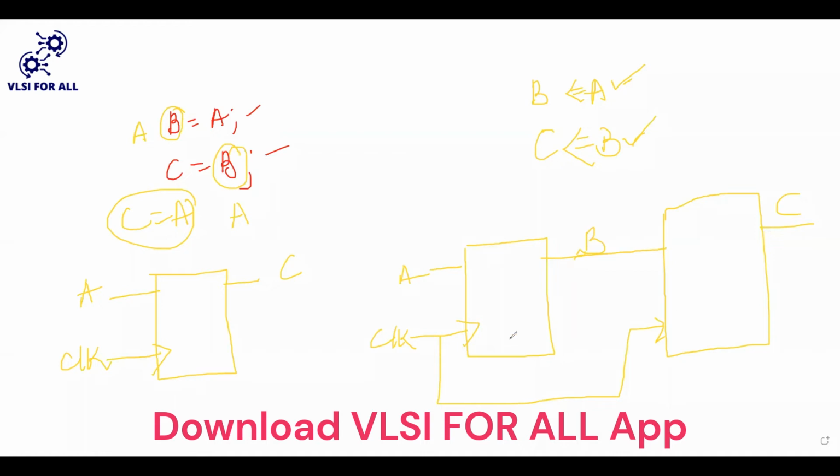Here there are two statements and it takes two clock cycles for the value to get updated. In the first clock cycle, the B value is updated, and as the earlier B value is not updated, the value of C will be don't care, as these are reg variables. In the second clock cycle, whatever the value of B is will be assigned to C. That is how one flip-flop is needed for this, and two flip-flops are needed for this.